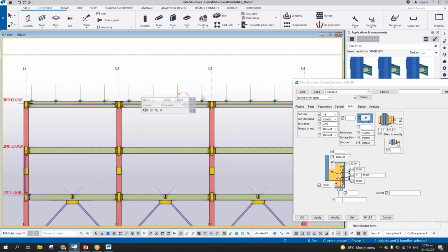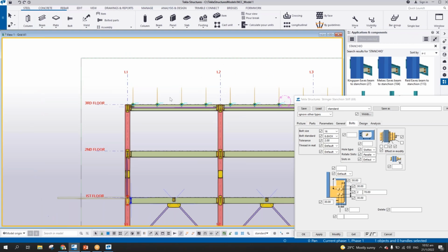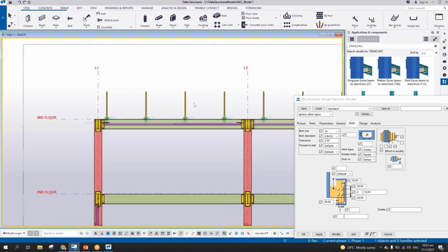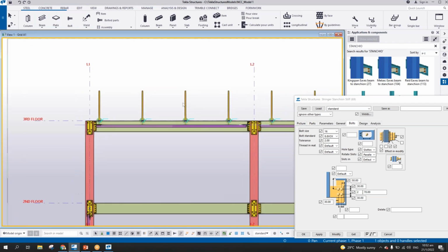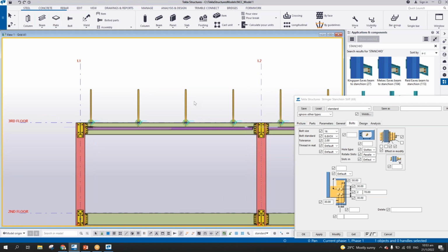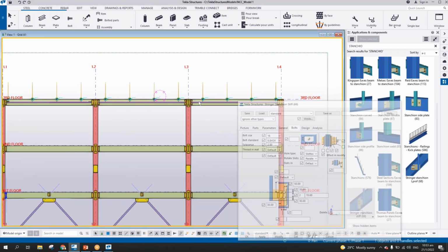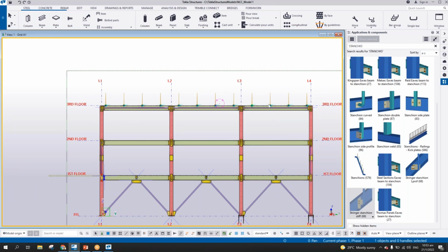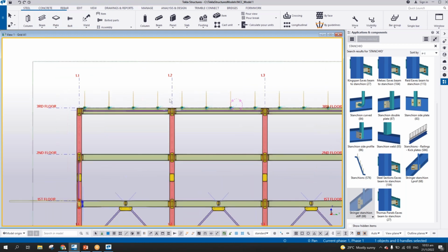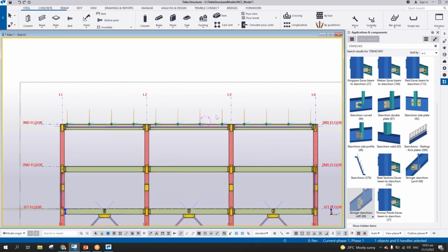Okay, so the next part will be the top rail. Basically in handrail, there is a maximum limit of the assembly that you can create. So meaning we cannot create the whole assembly for this 17 meters. Okay, so most of the time the maximum delivery or shipping length is 6 meters. So meaning in this case we can divide this one into 3.